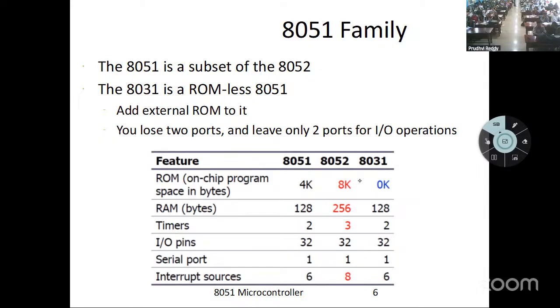8031 is ROM-less. This question may come in the objective or any competitive exams. What is the difference between the 8031 and 8051 microcontroller? The 8031 doesn't have any permanent memory, and the remaining features are the same. That is the basic difference. Okay. Next, coming to this 8052.